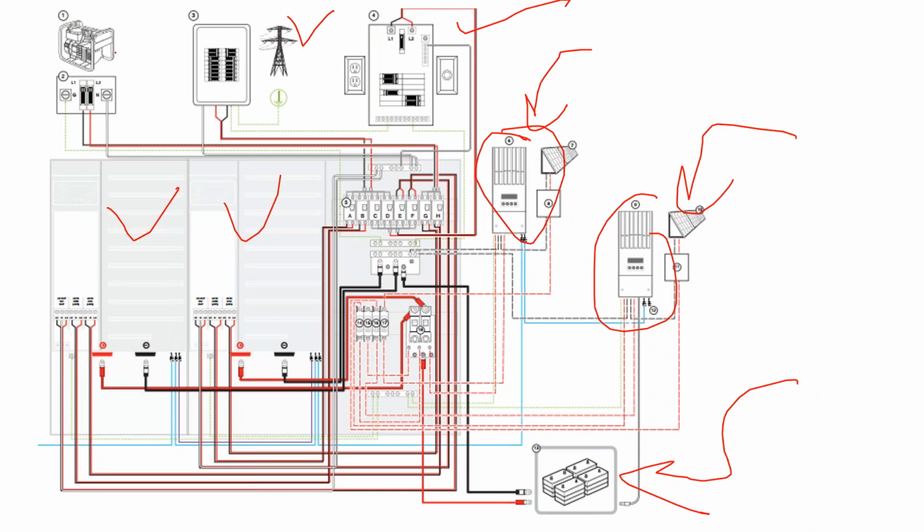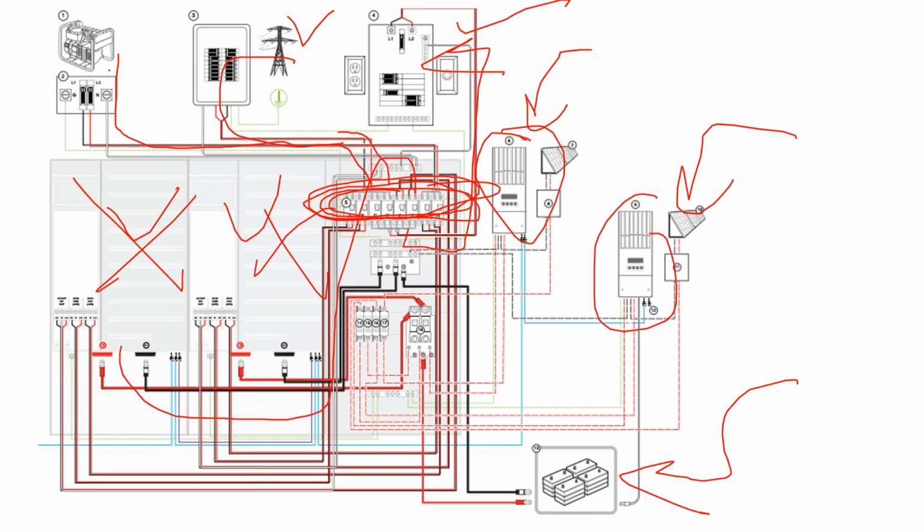This is showing the generator coming in from the top, the grid coming in from the top, the inverter outputs coming in from the top. This goes out to your load panel, and then there are bypass switches up here so that you can turn the inverters off and keep running off the generator if you had to place anything into a service mode.